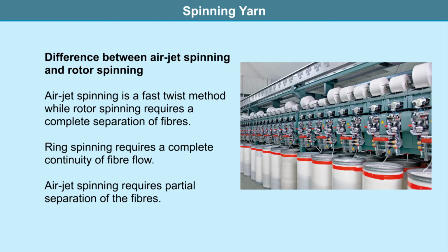Plastic starter bobbins containing a small amount of yarn are stored at one end of the frame. As the starter bobbins are automatically fed onto the machine, a movable splicer picks up the starter yarn and splices it to the newly produced yarn tab at one end of the numerous spinning stations on the frame.